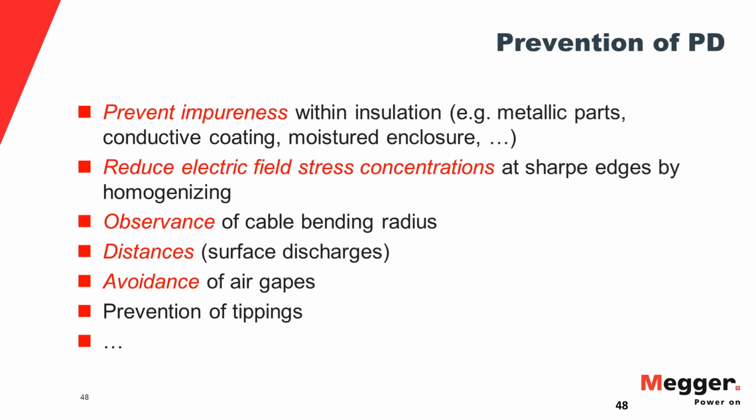Well, you do a good job, actually, and you make sure that your splicers are educated very well on the different splicing technologies. See, there's a saying in Europe, specifically in Germany, the wealth of the utilities is underground. Because if you do the installation properly and you have a very good cable from the beginning, and the jacket is undamaged, so you did your sheath fault testing as well, then you have a printing press, kind of, because the asset is there, minimum maintenance, especially on the latest generation tree retardant XLPE in terms of water treeing.